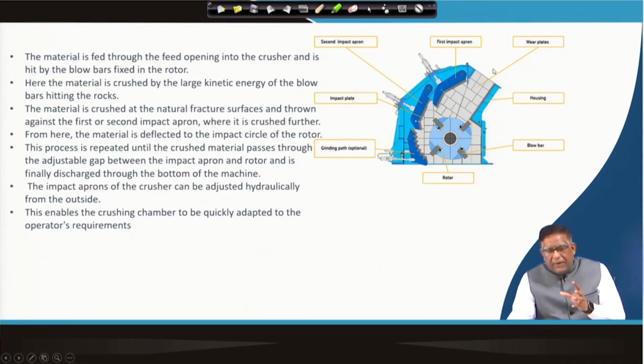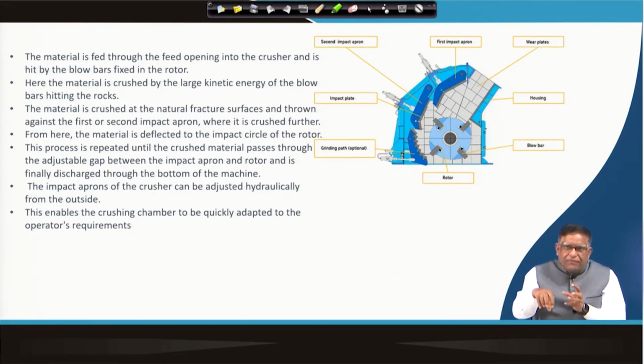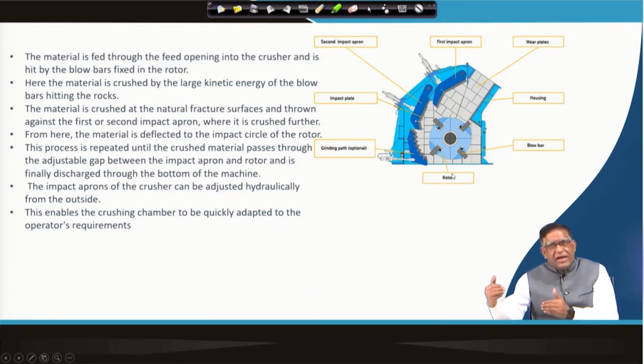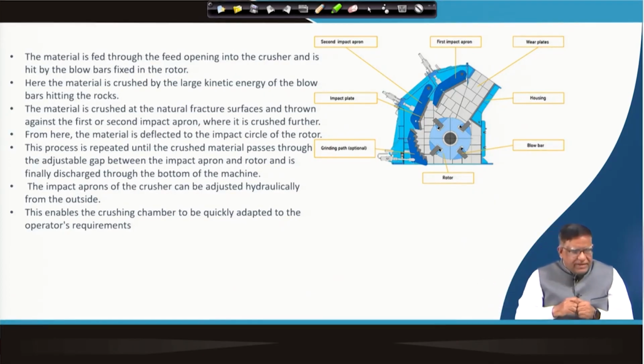is called the retention time. Depending on that retention time, the feeder belt which is feeding the material over there, at what speed it will be coming will have to be compatible. So, that is when you will be studying in a field, this needs to be matched. So, designing your crusher will also require designing how the feeding is taking place.